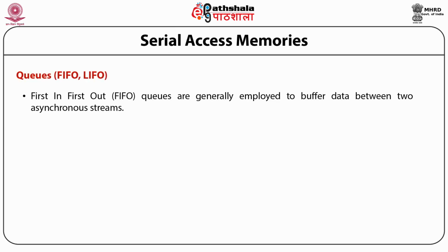FIFO means first in, first out. These queues are generally employed to buffer the data between two asynchronous streams. Like a shift register, FIFO is organized as a circular buffer. FIFO becomes empty on reset and both the pointers, read and write, are set to the first element.